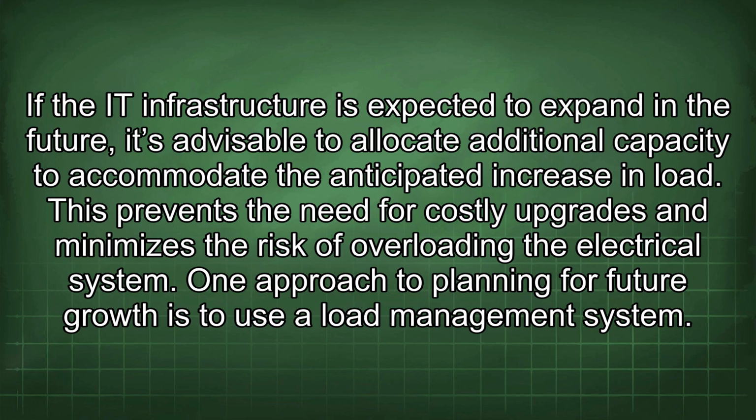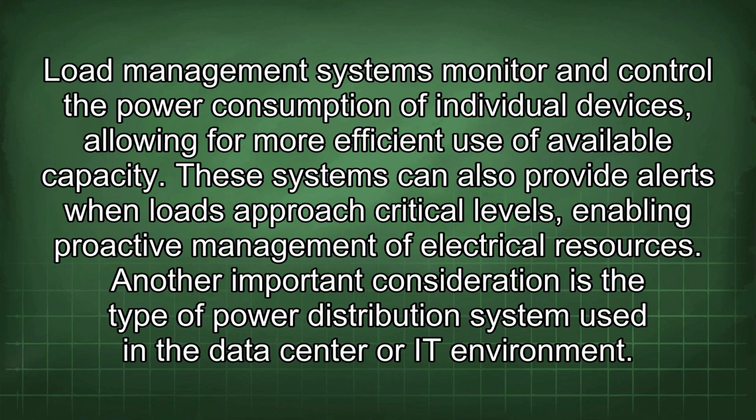One approach to planning for future growth is to use a load management system. Load management systems monitor and control the power consumption of individual devices, allowing for more efficient use of available capacity. These systems can also provide alerts when loads approach critical levels, enabling proactive management of electrical resources.